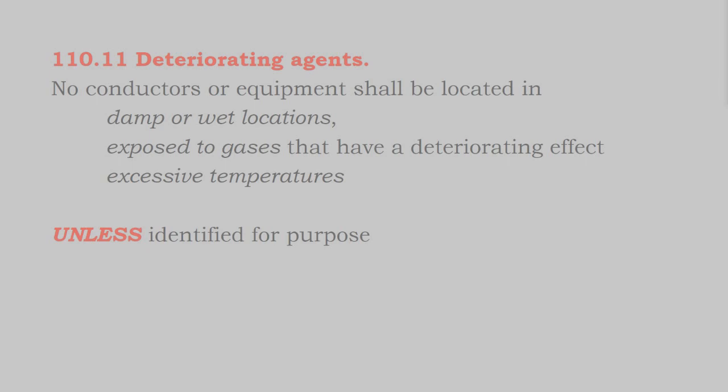You can have interior wet locations. A wet location is something that gets sprayed with water. So a car wash might be enclosed, but that would be an interior wet condition. Usually, a rooftop would also be a wet condition.